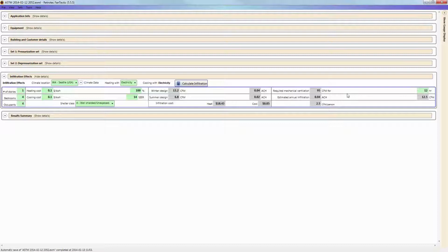So usually with ventilation rates, they tend to build up over fairly long periods of time, and as long as you get your average daily ventilation rate, then it seems to work out fine. There's a certain amount of internal pollutant loading that you can get. It's obviously better to ventilate more when there's more people in the house and more activities and so on. So there are some variables there, but there is a certain amount of momentum in the air change in a building. The air doesn't go bad immediately the moment 4 people show up. So this ventilation can occur over a prolonged period of time.